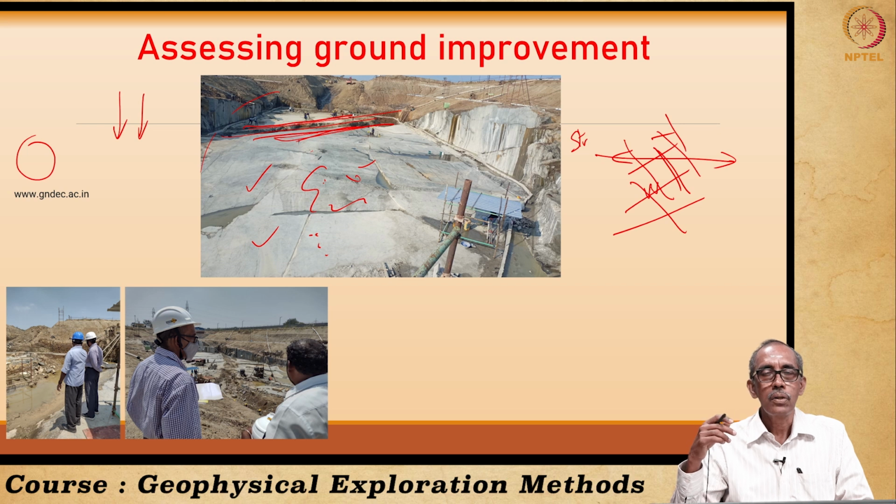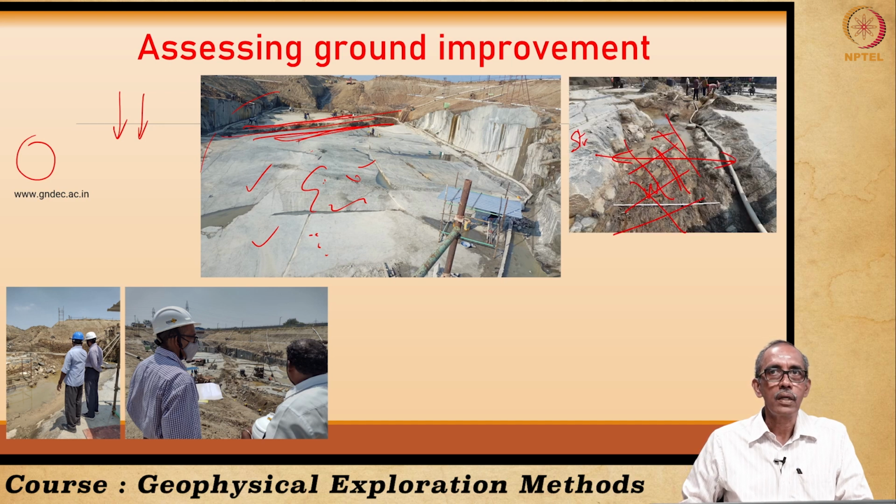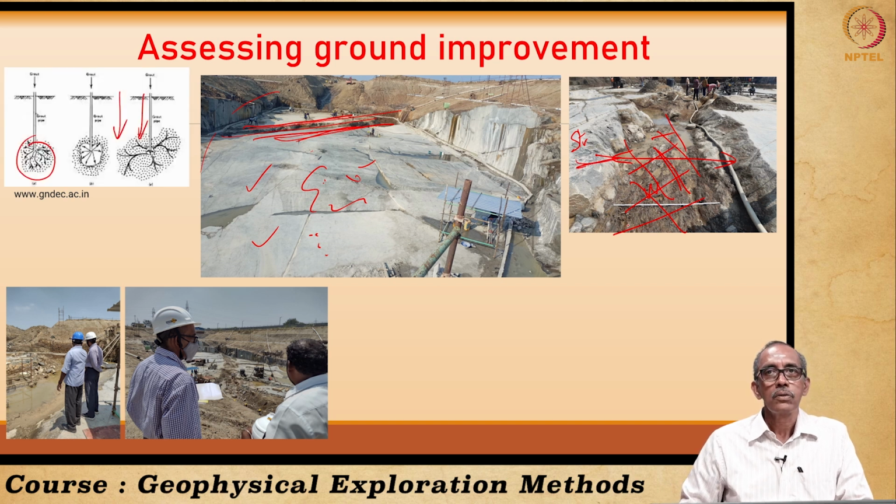and also at another site where we had carried out a foundation strata mapping, we came across sites where there were some weaker zones. This is what you see. We have massive rock on either end, whereas in between there is a weaker rock. So over there, we recommended improving the ground.